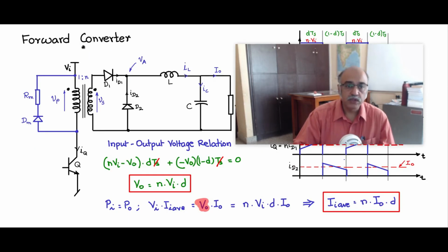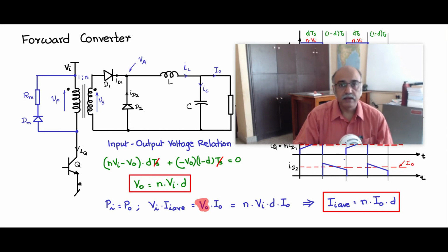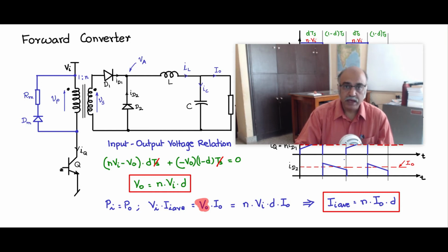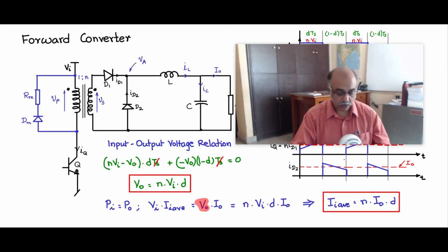We have seen also in the forward converter there is this BJT. Now we have shifted the BJT from the rail based to the ground based, saying that the drive circuit is simpler if it is driving a ground based switch. We will see all those issues, why it becomes simpler to drive a switch which is ground based.